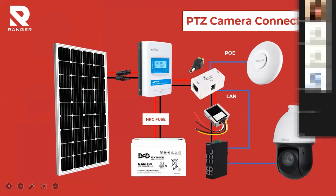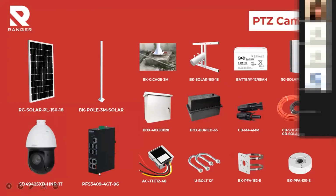To get the 48 volt, you must use this converter to convert from 12 volt to 48 volt. The LAN uplink from this switch can be connected to this LAN. So for PTZ, the difference is just to add this converter and this PoE switch and camera.